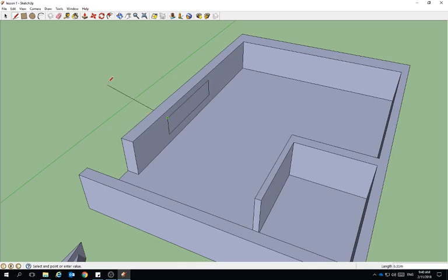If it goes off black, or if it turns blue like it is now, it's going straight in the air. I definitely don't want it to be green because it's going out the wrong direction entirely. So red is where I want. I click, it's done a line, and the pen tool always wants to keep on drawing line after line. So you can press escape, it stops that, but it's still got the pen tool selected.